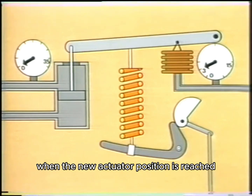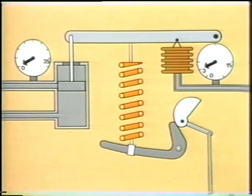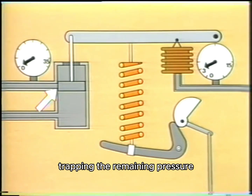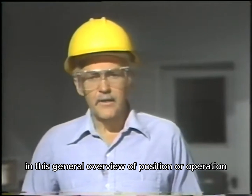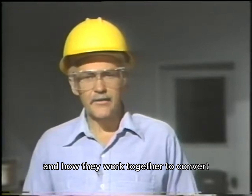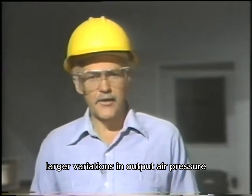When the new actuator position is reached, the force of the spring once again exactly balances the force of the bellows. The pilot valve closes, trapping the remaining pressure and holding the actuator in its new position. In this general overview of positioner operation, we've seen the basic components of a typical positioner and how they work together to convert small variations in control air pressure into proportionally larger variations in output air pressure.